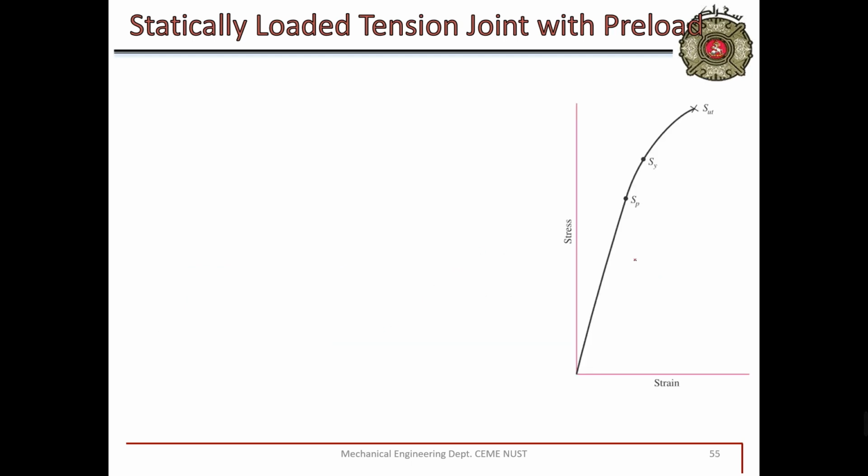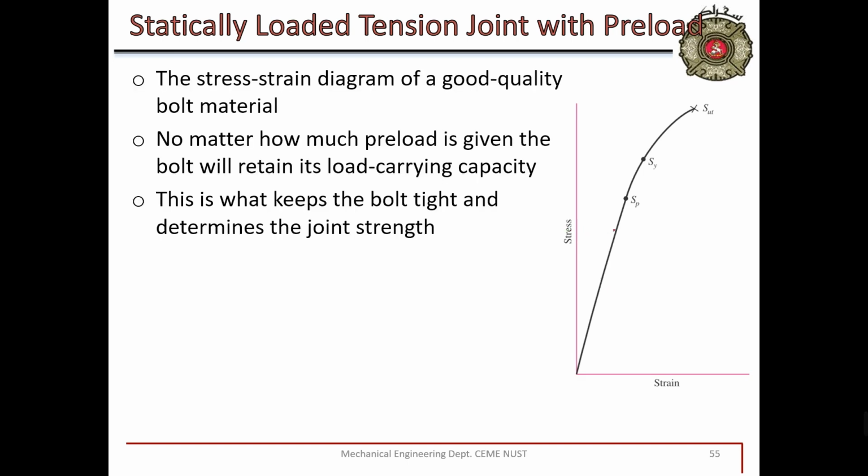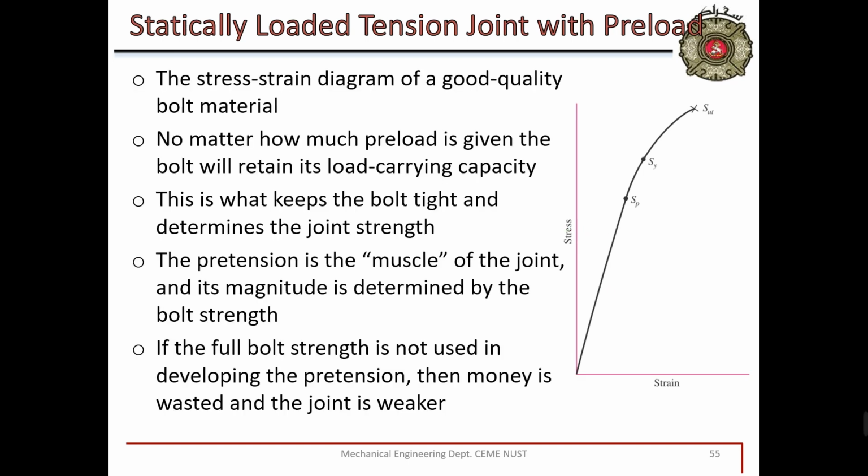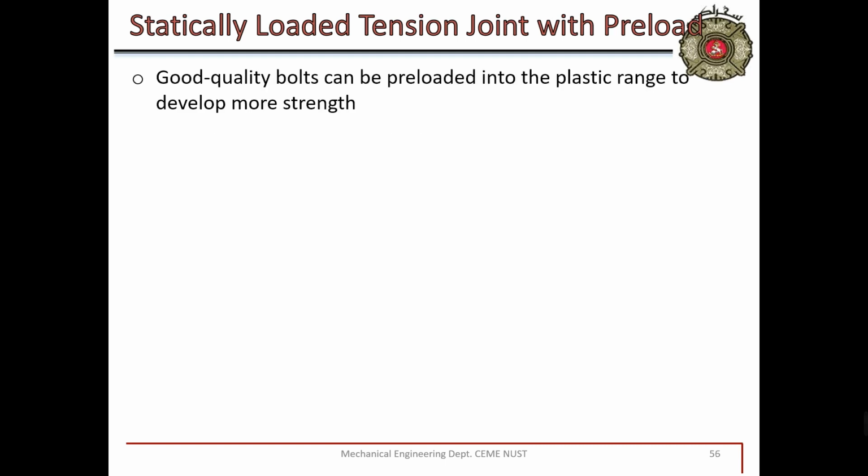After that, we had this curve, we have studied this curve, and this curve at the end only states that if you are tightening a nut and bolted joint, it will either fail during tightening or remain intact. If it has not failed during tightening, it will never fail.